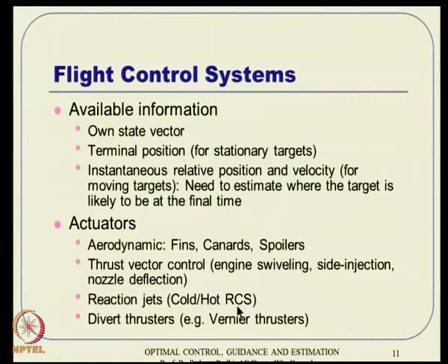Then there are reaction jets. Okay, you can also talk about cold RCS or hot RCS like that. Cold RCS means you have just pressurized gas and you let it go to expand through a nozzle. Whereas hot RCS means you actually have a small rocket engine sort of thing, where you actually burn and get your thrust and then deflect it through different jets and all that.